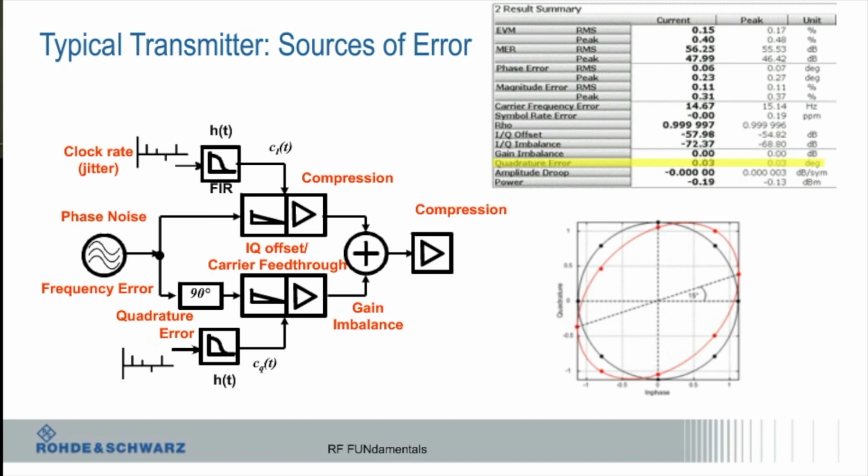So if you have a huge error in, say, IQ offset, and you tell it to do IQ imbalance compensation, and that goes away, then you know that's something I need to be looking at in terms of my receiver design. Do I need to provide the actual expected value of that? No, it calculates that itself. It calculates the ideal case. Yes, correct. Okay.